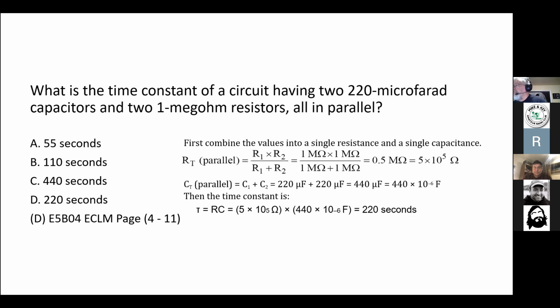Don't put your hand in there right away, even if you've discharged the capacitor. Let it calm down. Give it sometimes even a half hour or more on the high power. If you're running a linear at 1500 watts, full can, turn it off. If you have to open it up and look at it, keep your hands out of there for a half hour or so. That's the basic thing behind it, and this formula will tell you how long you have to keep your hand out of there.